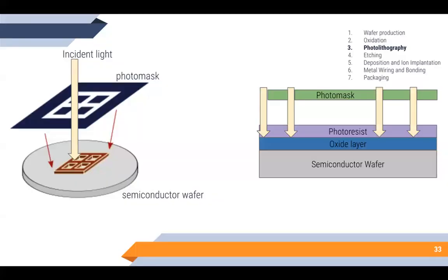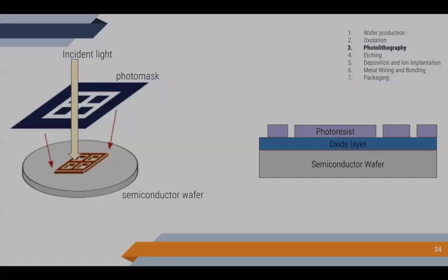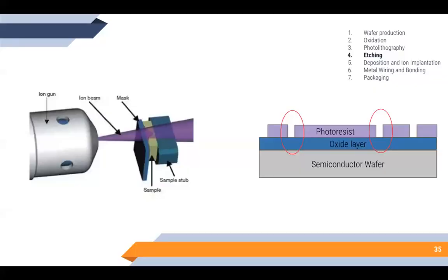In order to transfer the photomask onto the wafer, a photoresist, a material that responds to light, is applied thinly on the previous layer. Now, with the transmission of light, the pattern photomask creates a circuit on the wafer surface, seen here. Now, there's a lot of unnecessary material on the wafer. So the etching process, which is employed right now, carves out only the designated circuit pattern.